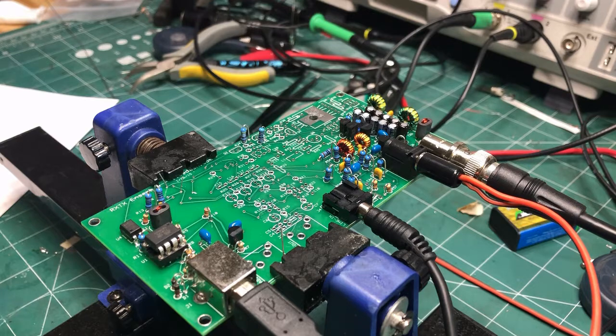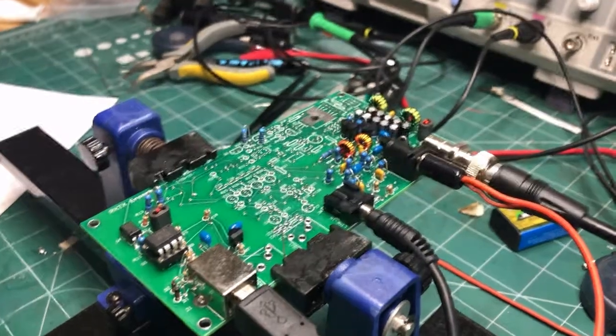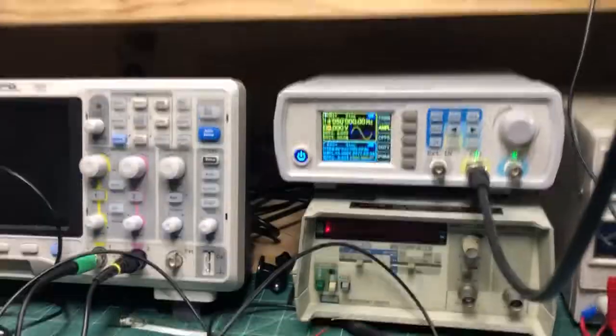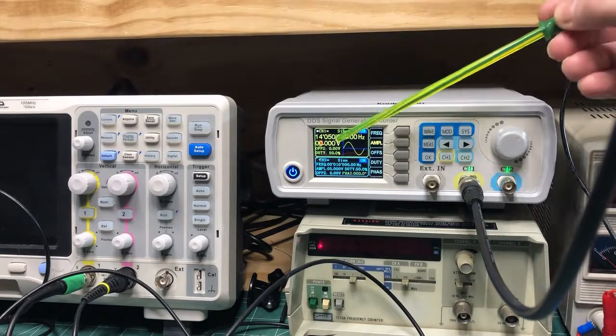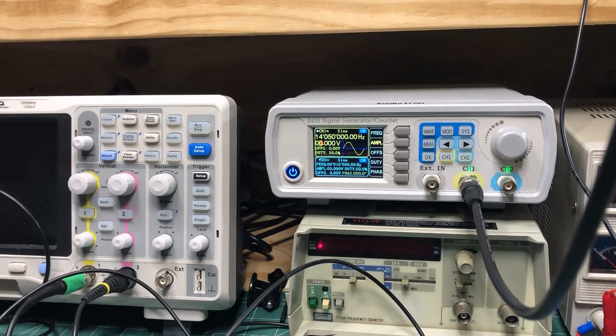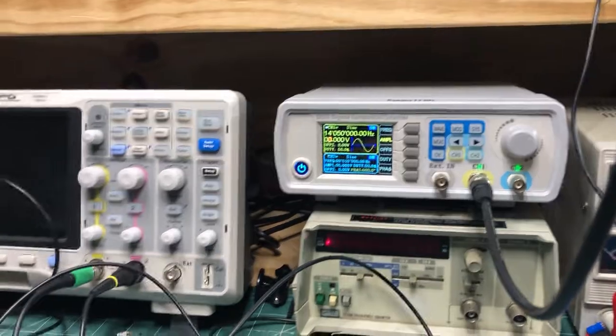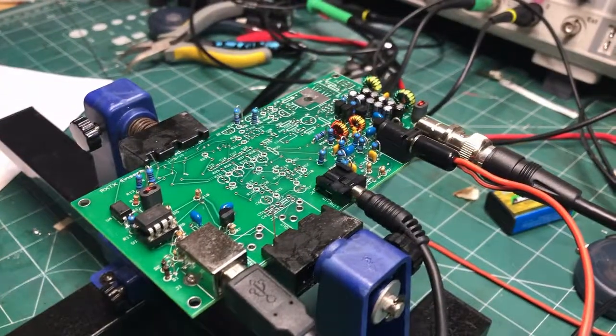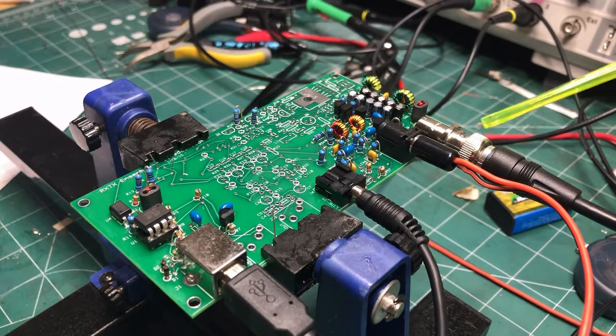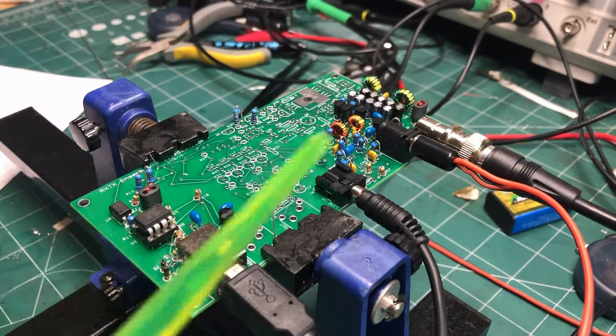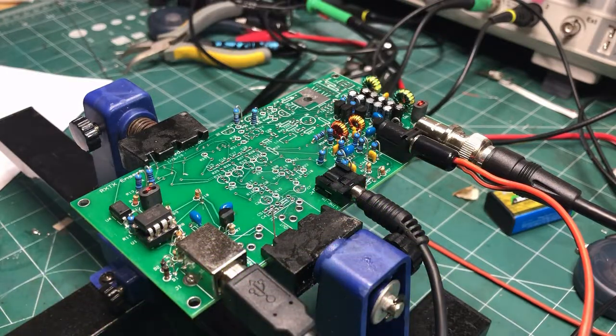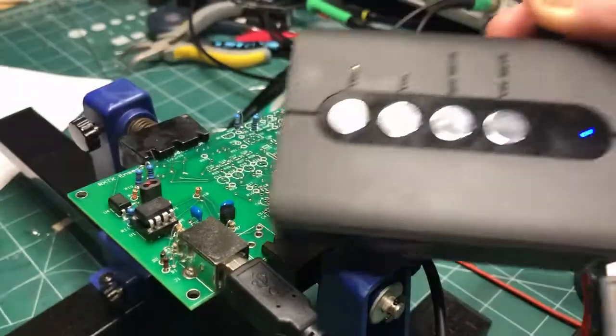So let's go over the setup that I have here. So what I wanted to do is, before I actually take this on the air, let's just test to make sure the HDSDR is all set up and we're receiving a signal. So just like in my previous video, I've actually got the signal generator generating a 14.050 megahertz signal. That signal is coming in to the radio through the antenna jack here. I have the I and the Q audio signals coming out here and going into this external USB sound card here.